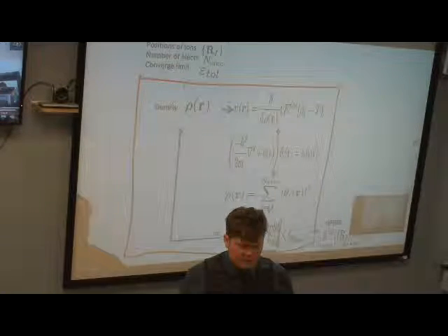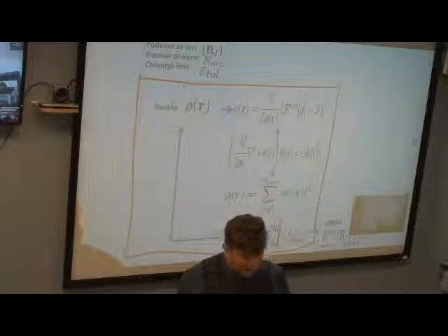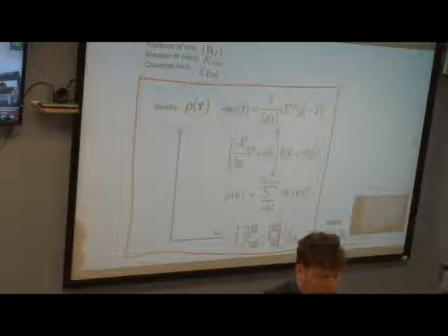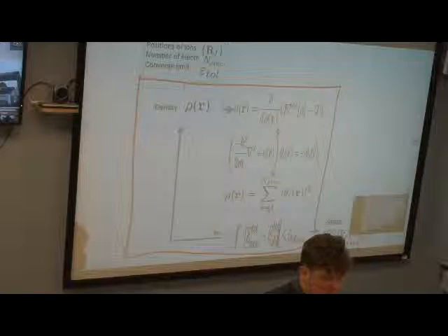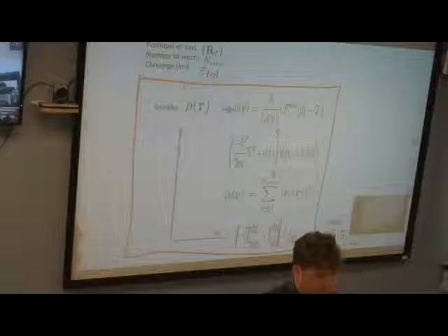So you notice that if you do orbitals and absorption spectra, first you need to do previous single point optimization calculations that give you a non-zero healthy WAVECAR, right? Did you ever try to run a specific template of the INCAR file for the orbitals in an empty directory where you do not have WAVECAR?